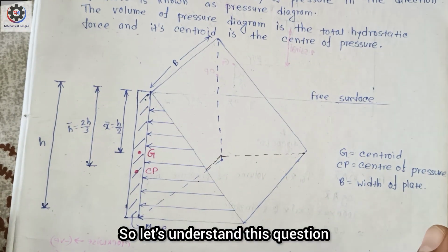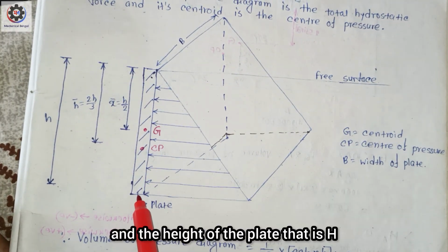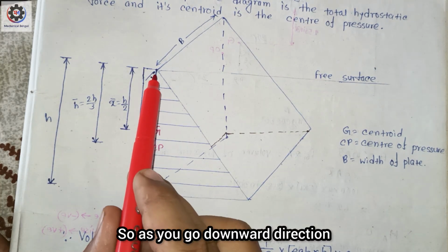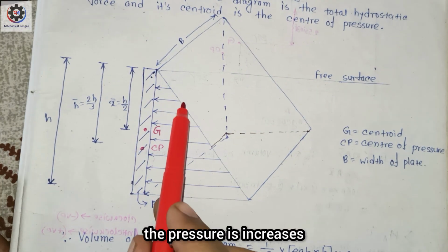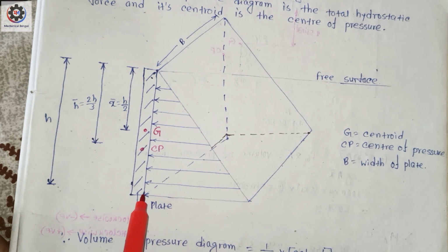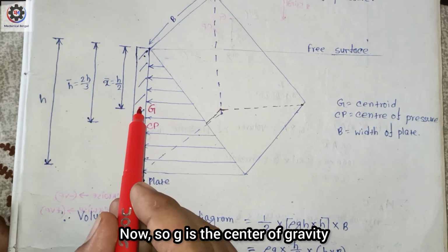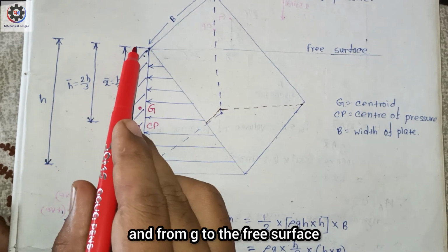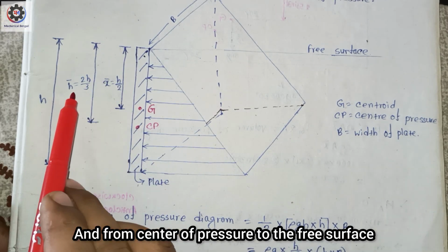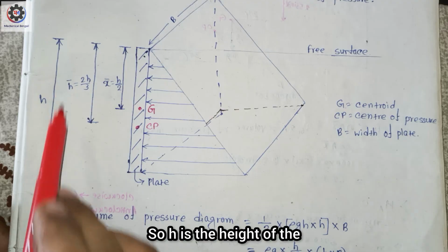So let's understand this concept. Consider this is one plate, and the height of the plate is h. As you go in the downward direction, the pressure increases. Here the pressure is the maximum, and that will be rho g h. G is the center of gravity, and from G to the free surface, x bar is equal to h by 2. From the center of pressure to the free surface is known as h bar, and h bar is equal to 2h by 3. h is the height of the plate.